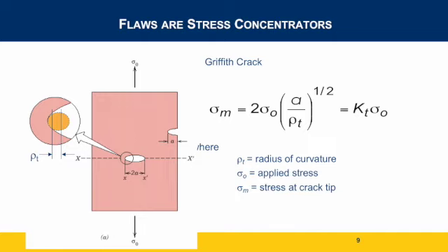Okay, so these typically occur because of some kind of void or crack at a point. These can occur quite commonly when we make materials, when we cast them at really high temperatures. So we have a lot of voids just from atomic vacancies that we talked about a couple weeks ago. We also can have other gases and things in there that are impurities that are in the way when we try to cast these materials, and it could leave spaces or voids within or on the edges of our casted material.